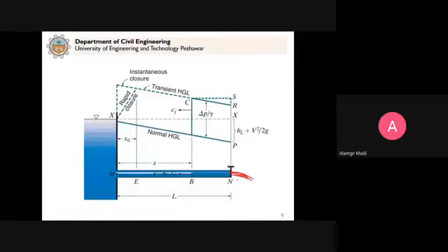When this happens, we have this normal pressure variation diagram. This is the pressure distribution diagram considering the friction in the pipe. When we consider the friction in the pipe, this is the sloping normal hydraulic grade line, because at every point it gives you P by gamma. This is P by gamma here, at any point, and so on. So this is the normal situation.